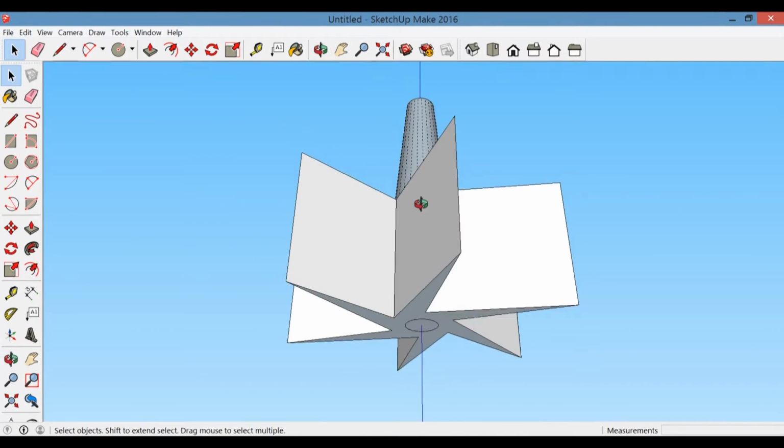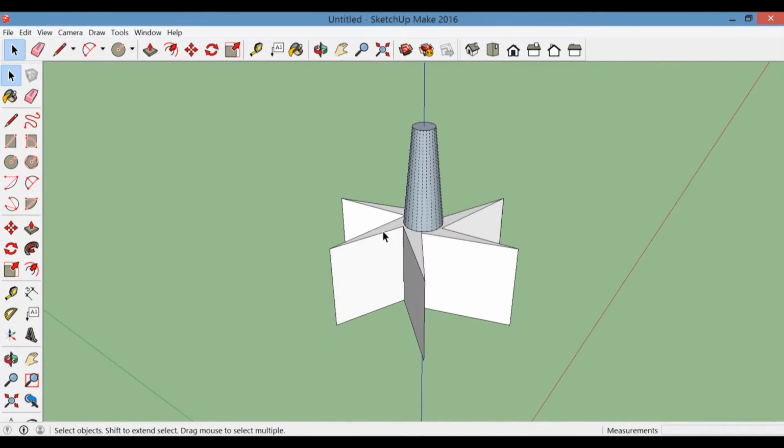And after you've done that, you'll want to export your model. So most 3D printers recognize the .stl format for printing. And normally, if you provide your teacher with a file to print in the SketchUp native format, they'll convert it to an STL format for you. But if you don't have that kind of resource, you can use SketchUp's own extension to convert files.